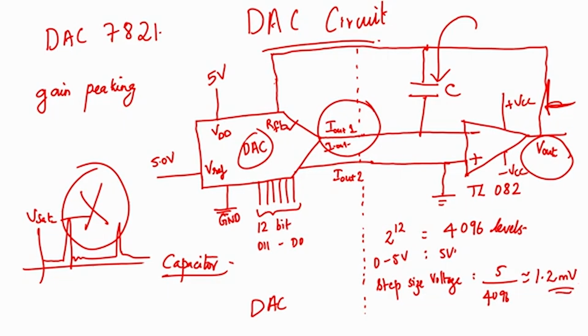But then there is one more thing, because we are using an amplifier stage and it is a negative feedback amplifier, and we do not actually have a feedback resistor, we have a capacitor only in the path. So, the maximum amplitude may get reduced when we actually practically implement it. That has to do with all frequency changes, noise levels, everything in the circuit.